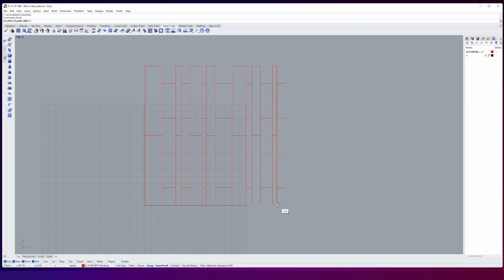So what I'm going to do here is take the bottommost right extent of my pattern and just add a point there so I know that's the bottom right, and then we have the top left up here. I'm going to type in distance, and I'm going to measure the distance on my X value, or sorry, we're going to do Y value first. So I'll measure my Y value distance. You can see here it says 96 inches.